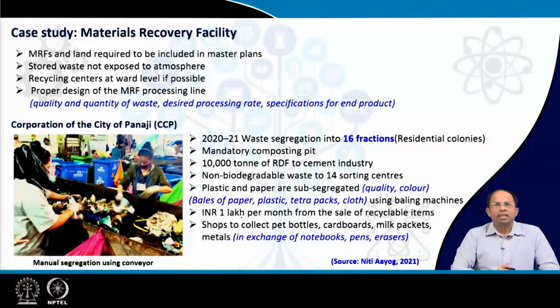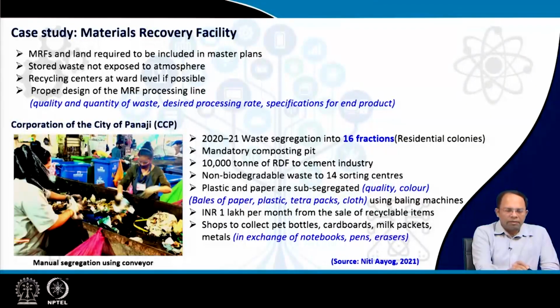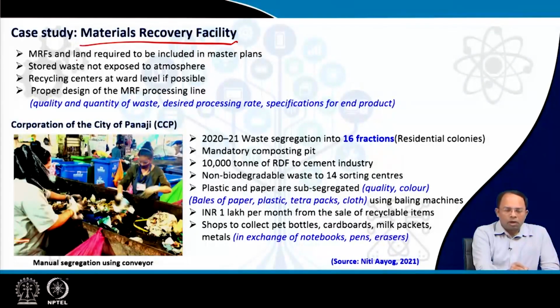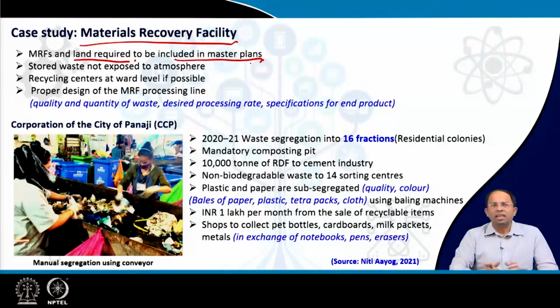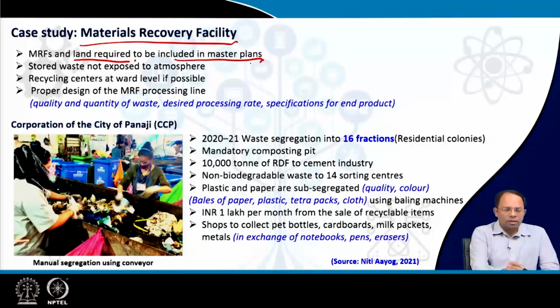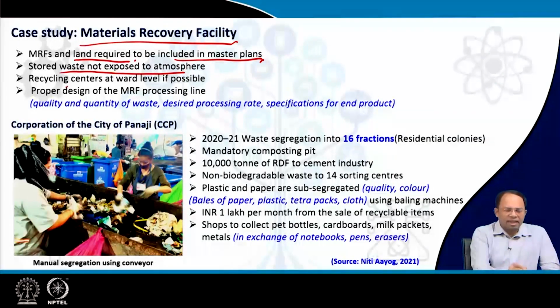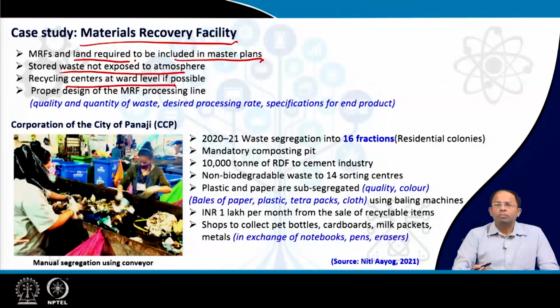So now we will talk about some case studies. Whenever we are talking about setting up material recovery facilities, we have to decide what amount of land is required, and we have to include this in our master plan. That means in master plans we have to make provisions for the land required for setting up these MRFs within the city itself, maybe the decentralized ones. Stored waste within the MRF should not be exposed to the atmosphere, so of course it should be within sheds. Recycling centers should be set up at ward level if possible; if not, at least one facility for a group of wards.